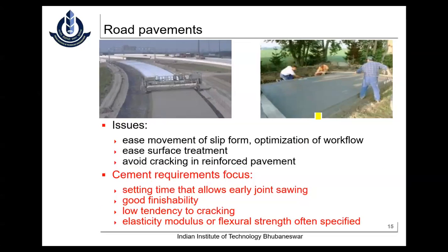Nowadays, for durability purposes, nobody is blending at 15-20%, sir. People are around 30-35%, 28%, 30%, in that range. Every cement manufacturer manufacturing a PPC cement, their blending is always around 27, 28, 30%, 32% like that. Some are even going higher. Just for the broad range, usually these codes initially started off with 15%, 20% blending, and that has been retained actually. That is why they have given this broad range.